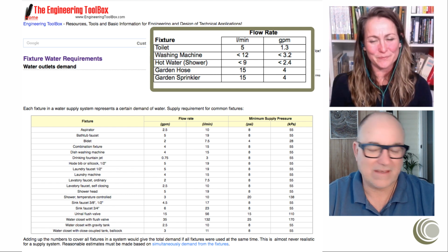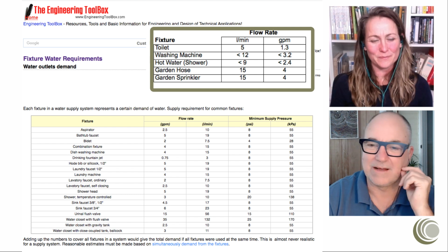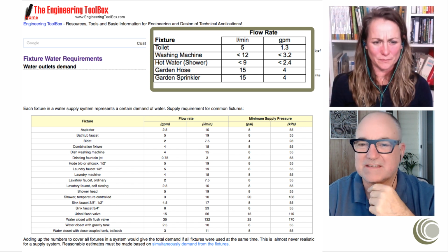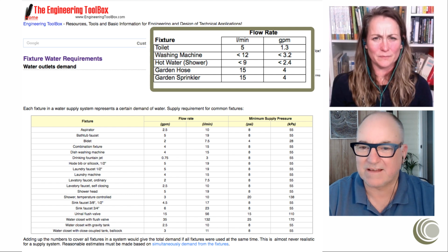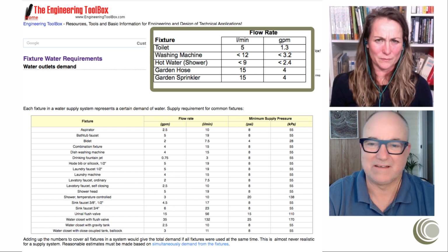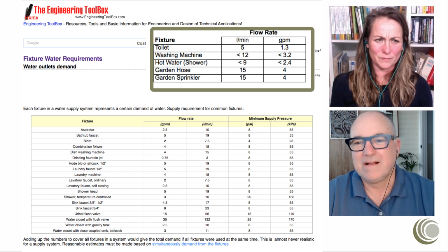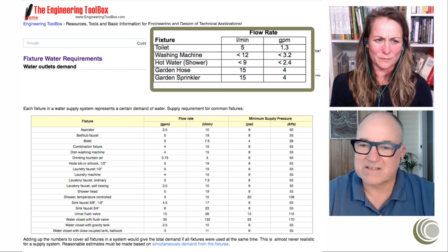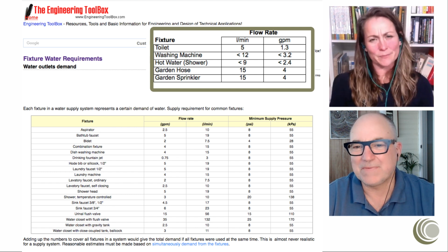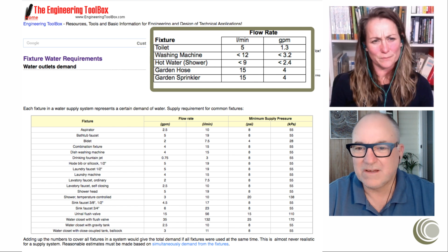And if your house has many bathrooms, and we've been watching these design programs from North America, and there seems to be a lot of bathrooms in North American houses. Just because there's 4 bathrooms, it doesn't mean that 4 showers and 4 toilets are all operating at the one time. So you've got a little note here, Michelle, that assuming that 2 appliances could be operating at the one time, and that's what I would do.